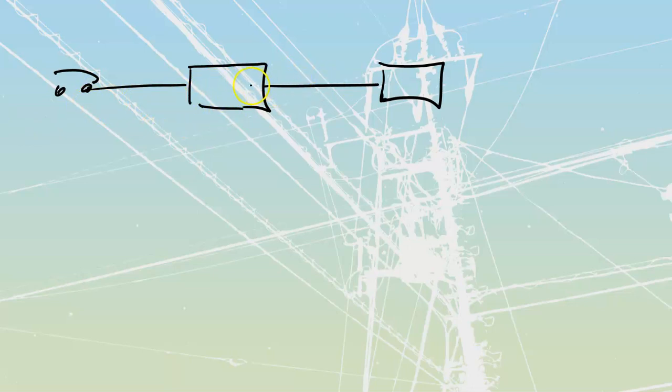If we feed off to other pieces, we need to overcurrent protect every time that we downsize. And we're pretty used to this because anytime that we're putting stuff into a panel, we're taking stuff off on a 15 amp breaker out of a 100 amp or a 200 amp or whatever the size of panel is that you're working out of. We're used to putting this stuff in for the bulk of our components.